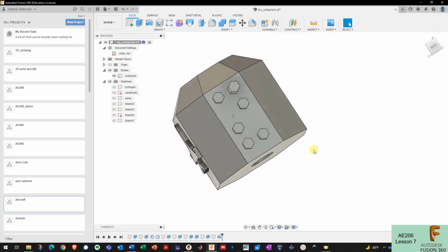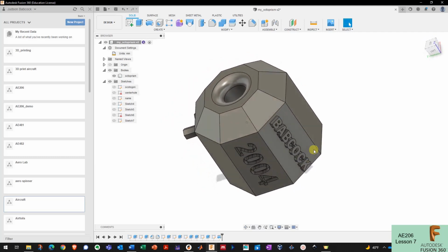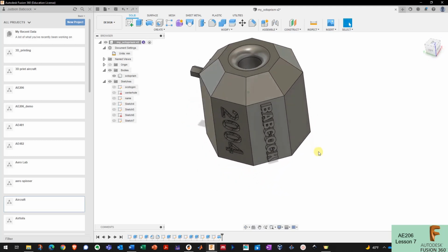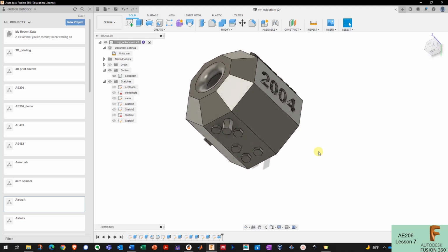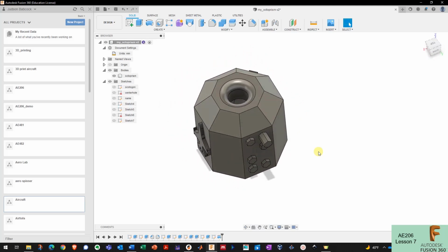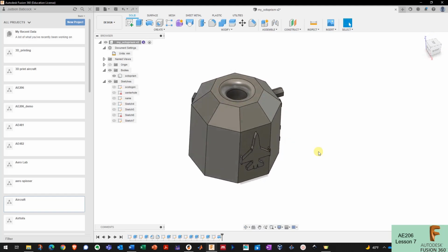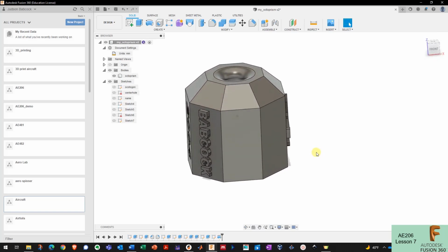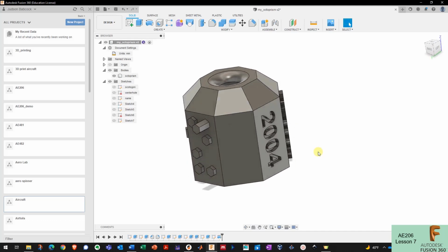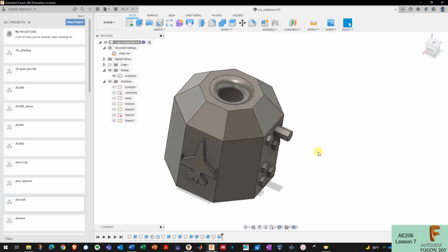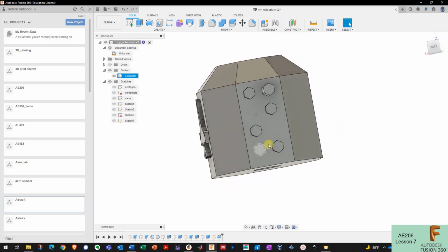And this is all as opposed to a very different type of model they call surface modeling, where we don't model the structure as a complete solid. We just model each surface of the structure to kind of create the shape and the look of the object. So surface modeling is much more free-formed. It's really powerful for just rapidly creating surfaces and getting something that represents what you're looking at. But there's no guarantee that those surfaces will all connect to each other and form a watertight model. And if it's not watertight, we won't be able to create a solid model out of it. And we won't be able to 3D print it, and we won't be able to do engineering analysis with it. So we're purely interested in creating solid models.